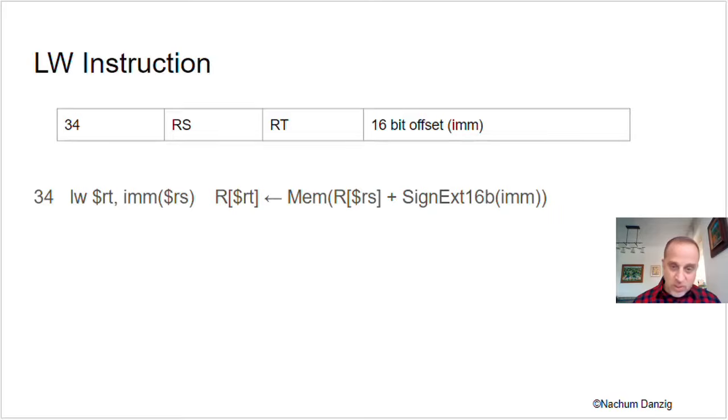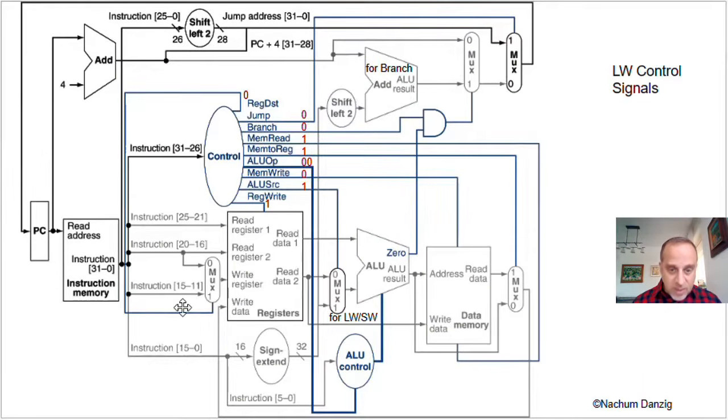So let's go back to our picture and see that we need to take, note that this is the RS, this is the RT, this is the RD. So we'll take the RT. We better have a 0 on this multiplexer. Let's see, do we? We go up, and there's a 0 there. Somebody nicely wrote in a 0 for us. Oh, that was yours truly. But there's a 0 there. So that means that we will, in fact, write to the RT the value that we chose to do.